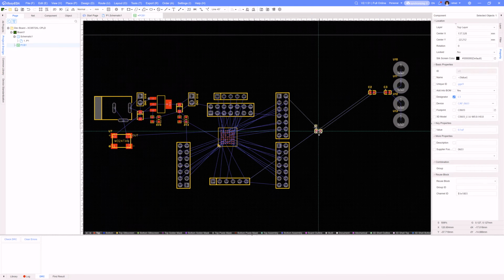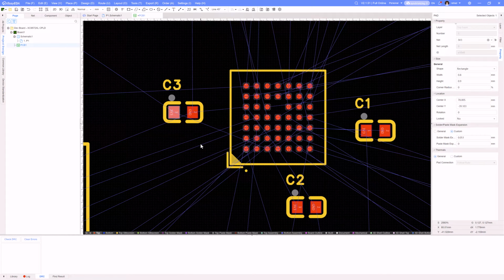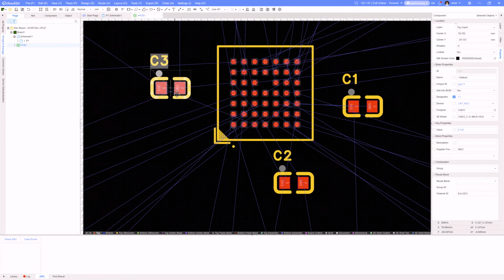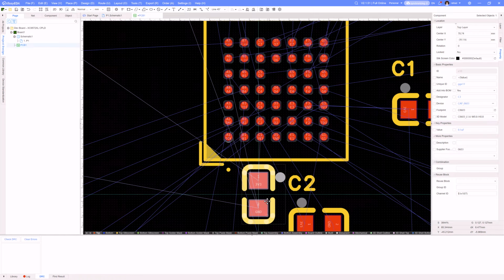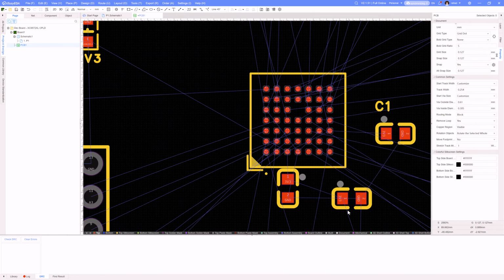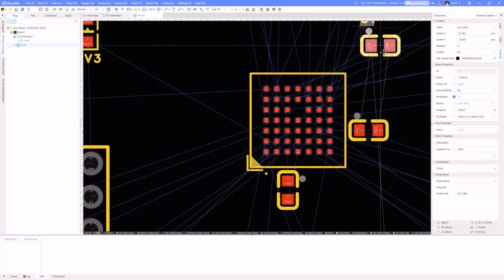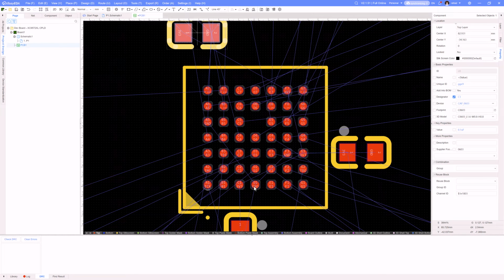Okay, I've got some capacitors. These would be decoupling capacitors for this CPLD. So I want to kind of see. Now these are 0603s for size, and you can see how big they look compared to this package. That just tells you that this is a pretty small package. But I've got a VCC line down here, so I might place this there. And here I have another one over here. And then there should be one more up here somewhere. So let's find that. I can hover over, let's say 333. Okay, so the other one is right up here.